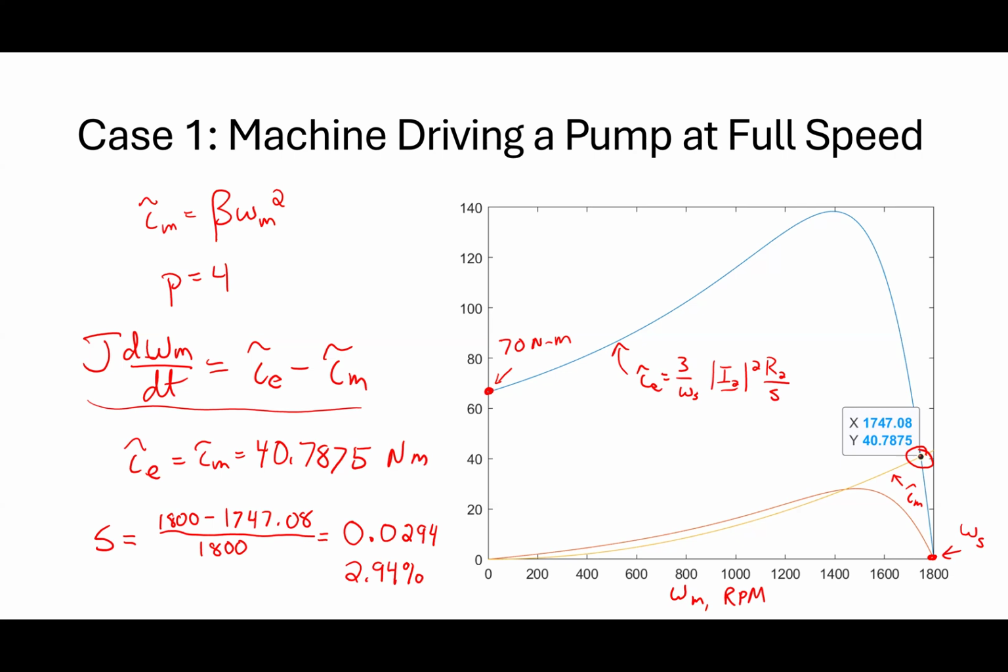That's about it. So we often call this guy a fixed speed motor because he doesn't really change the speed much in going from no load, and when I say no load, that's here, there's no torque being produced, to full load, which is there. This other curve I've shown here is actually the mechanical power, P mechanical.